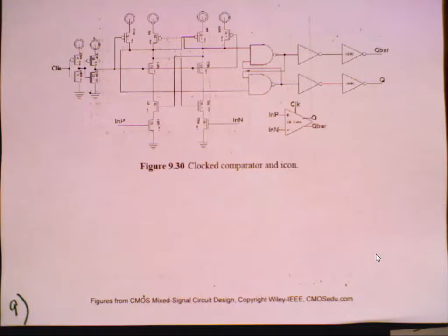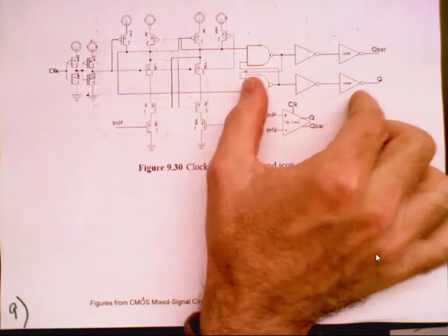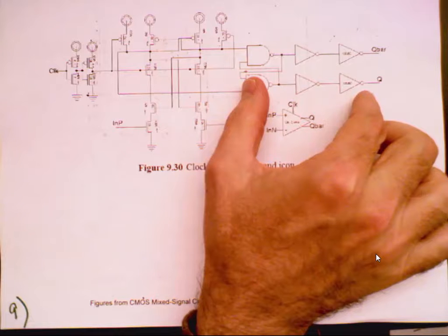But bottom line, were the comparators a problem in general? The inputs don't switch at really low voltage, so I had to preamp to let those out. The delay through it was the problem with the comparator itself. Well, yeah, the problem is, like you were mentioning, squaring up the signals here.